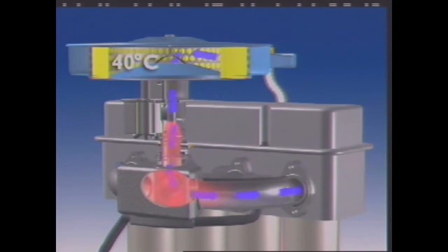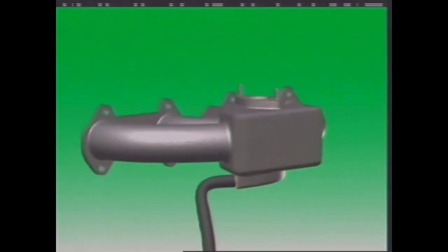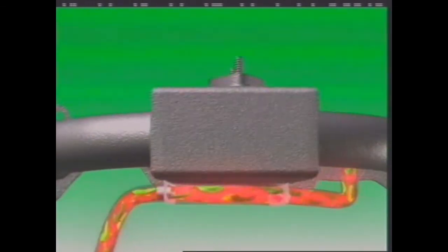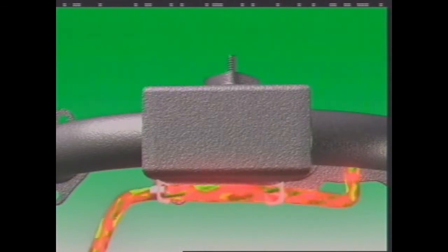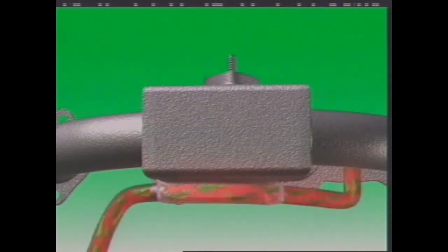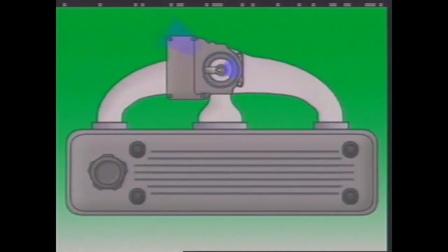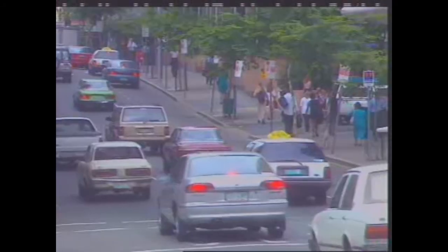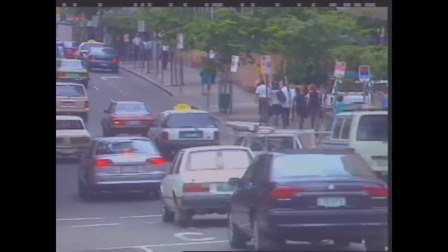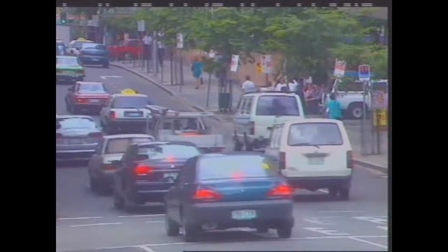Maintenance of this temperature assists vaporization of the fuel, particularly when the engine is cold. Vaporization is also assisted by heating the intake manifold, normally by circulating hot liquid coolant through passages in the manifold. If a manifold is too cold, fuel condenses on its inner surfaces, which will create a lean mixture and may cause incomplete combustion. Carbon monoxide and hydrocarbon emissions are highest from a cold engine.